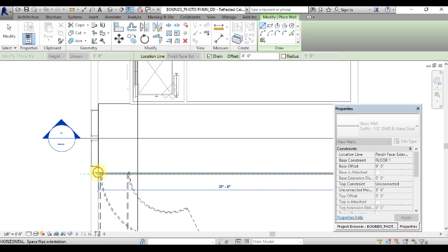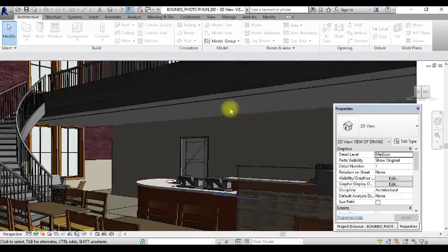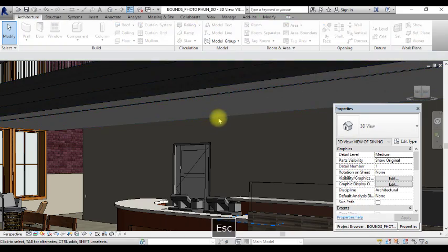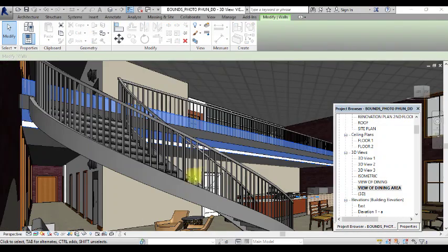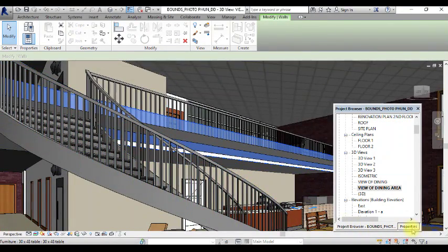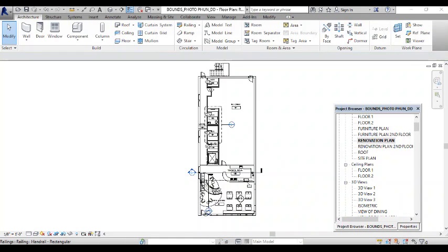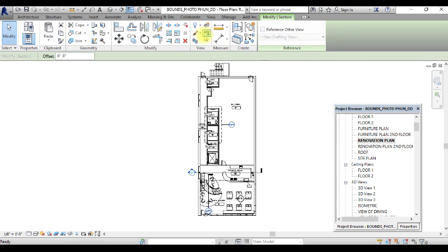And when I look at my 3D, or I could be doing this actually in another view, but here we see it here. It's kind of difficult to see it with this realistic view, but I've got my ceiling, and then I've got the soffit, and here we can see that better, and I'm touching it, and even in perspective view, I'm able to control how tall it is. So I'm going to set it down to be 18 inches, and so what it's done is given me a way to enclose the space between the ceiling and the floor of the second floor. And later I'm going to dress that up with a panel, but for now at least have that filled in there.